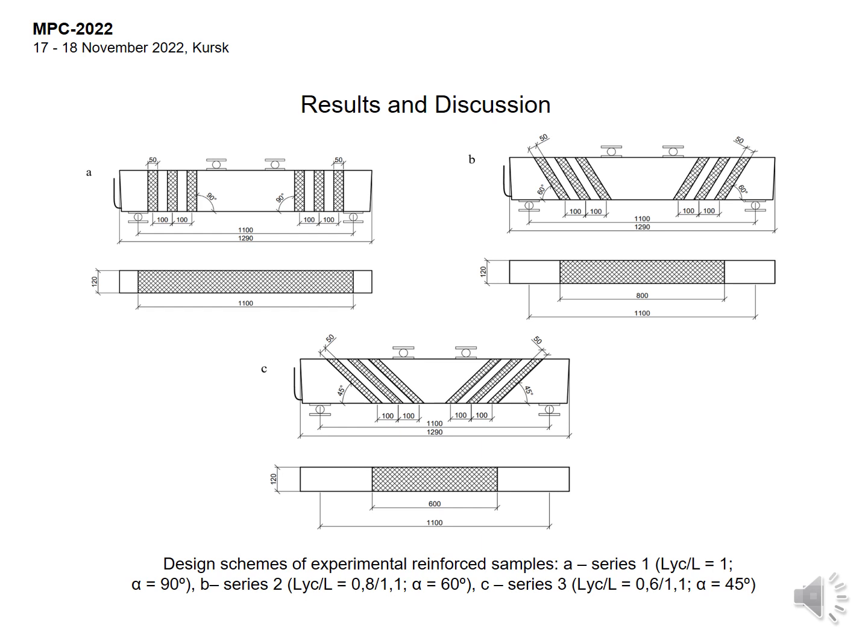The ratio of the length of the reinforcement section to the calculated length of the element was chosen as the variable parameter during the test, as well as the angle of implementation of the transverse composite reinforcement alpha. The transverse composite reinforcement in the element, while stretching the inclined section of the element, has the function of adhering carbon tapes in the stretched zone to concrete.